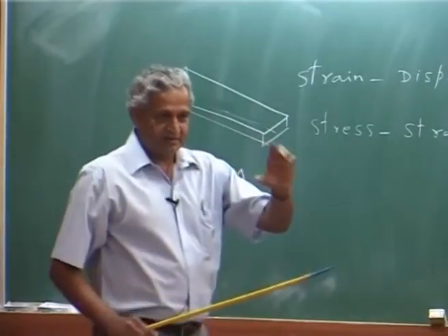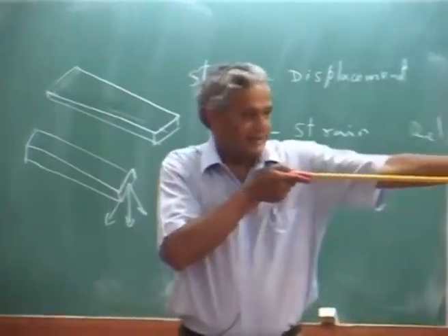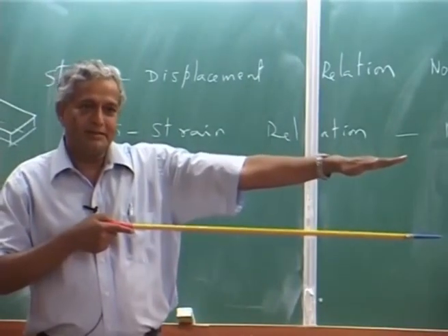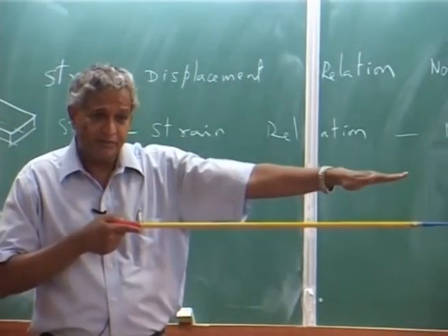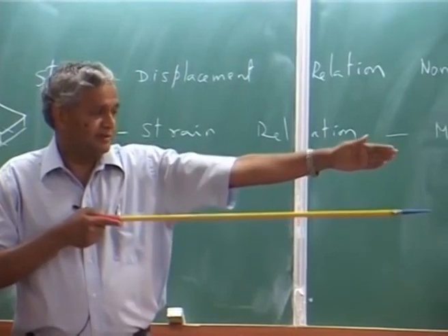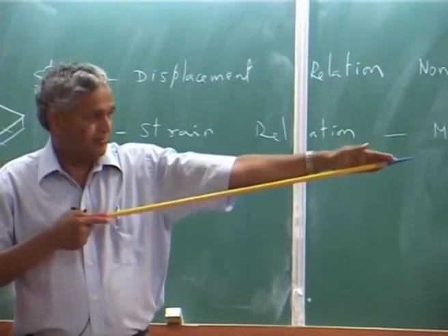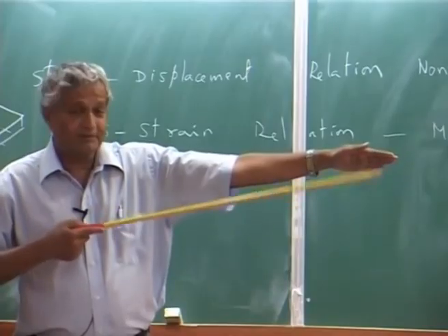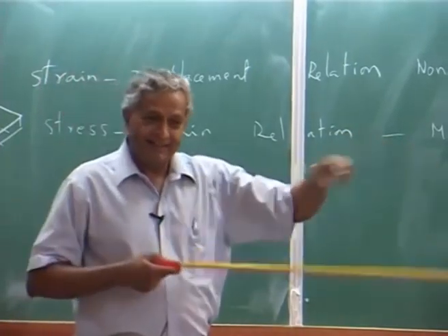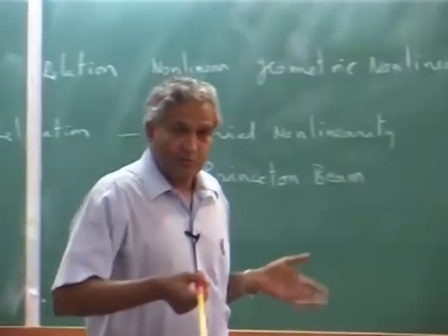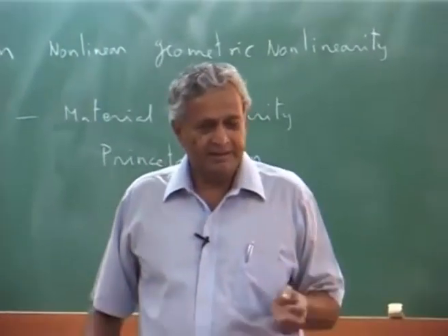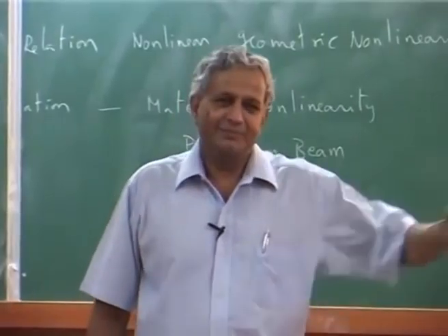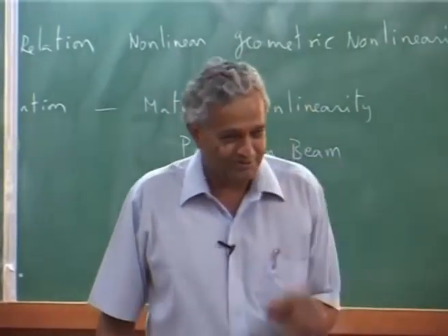If the beam cross section is flat, you apply the load, this is the beam bending. You want it to bend in both directions. So, instead of that, they just took the beam, kept it a little inclined, applied the load, that means the tip load will give deflection in the blade coordinate, in both directions. So, this experiment was conducted for slightly moderate deflection, large deflection you may call it.